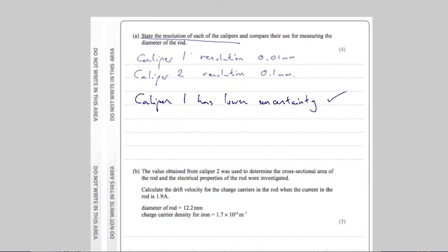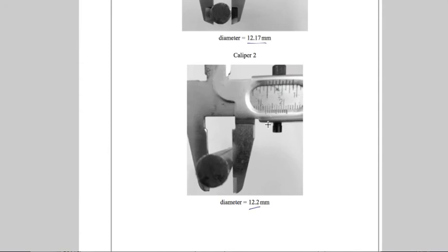That's certainly something we can say for a mark. Something else, well, let's see. Caliper 2, now this involves making a judgment. I don't know if you've used one of these vernier calipers, but we need to see where these small marks line up. And if we're making a measurement of 12.2, now we can see that the 12 comes in because we're at 1.12, so that's the 12, but then the 0.2 is because this second tick lines up. But that involves a judgment. It might well have been read as 12.1 or 12.3.